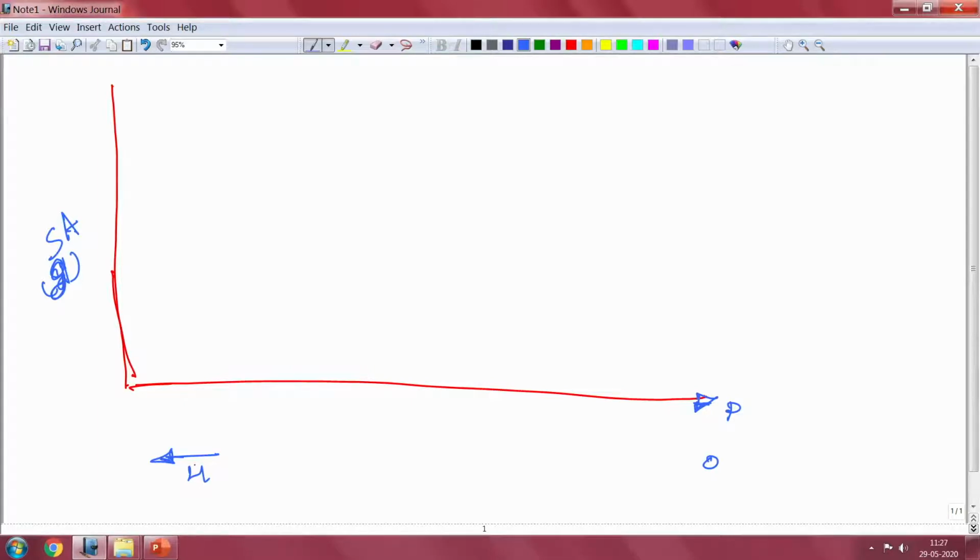So the fairly constant region is basically your high frequency range, where the acceleration is fairly constant, so it will be like a kind of slope. Then there is an intermediate frequency range, where there is a velocity constant. The displacement constant will be in this one. Okay. So this is how your response spectrum looks.